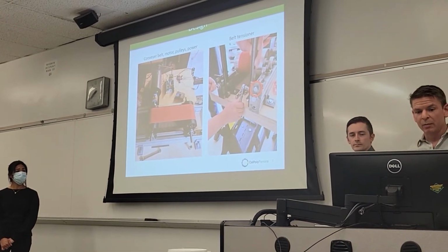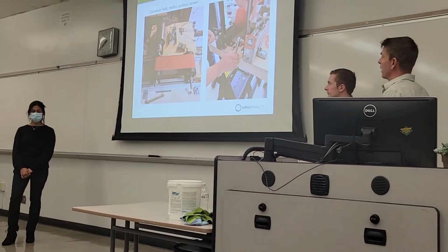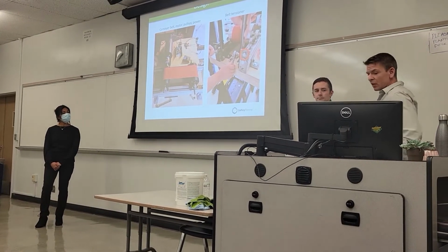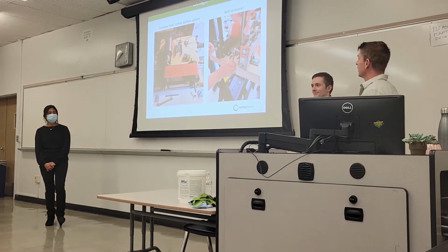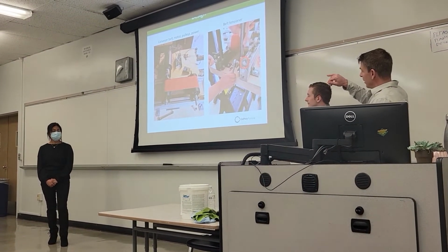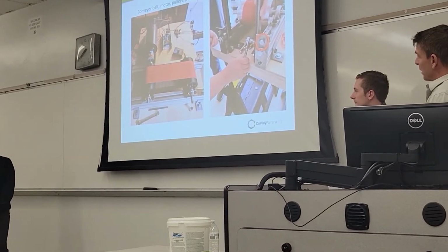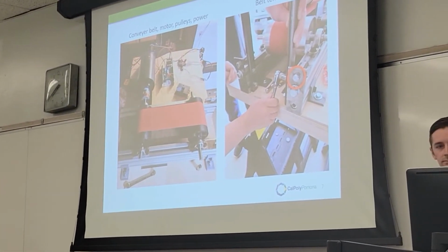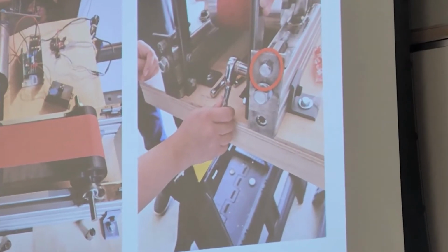And so here are some components of our design. As I mentioned earlier, we use a 4.25 horsepower motor. I'm sure a lot of you are wondering, why such large horsepower? Cost is an issue for this project, and it happened to be the cheapest motor we could find on eBay at the time to suit all our needs, so we took that one. So you've got a Lovejoy coupling right there in the drivetrain that extends out to 2 pulley wheels and a belt. We have an MC60 motor controller controlled by a potentiometer to adjust the speed. The picture on the right here is our belt tensioning system that's going to help with alignment and tensioning.